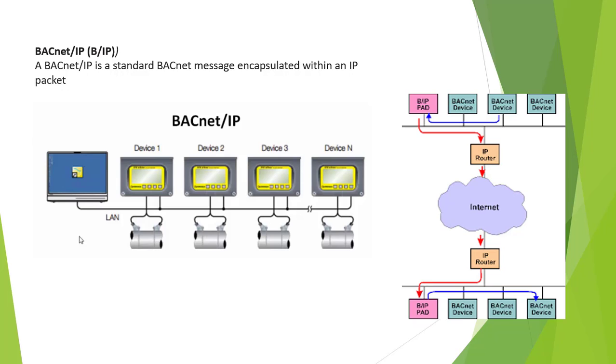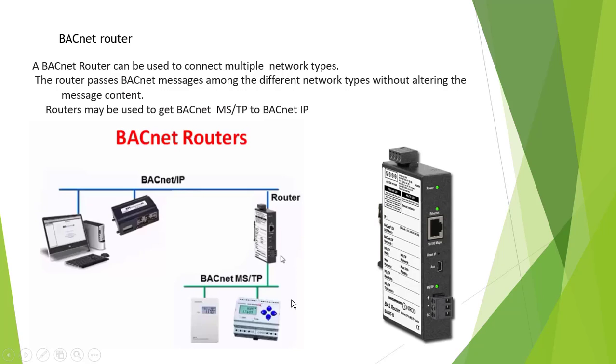This is BACnet IP. BACnet IP just uses IP packets, the same as the internet IP. The BACnet devices communicate through an IP router, then communicate with each other. So now we talk about the BACnet router and BACnet gateway.